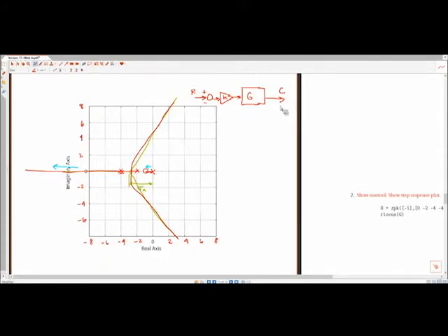When we say closed loop, what we mean is that we have now closed the loop by putting all the hardware in place to actually perform this action of closing the loop. And now we talk about closed loop zeros, closed loop poles. We're talking about this transfer function, C over R. Okay. Right. But then what we learned in the one homework problem is that if we have a set of zeros of G, those zeros are also going to be in C over R. Not the case for poles.